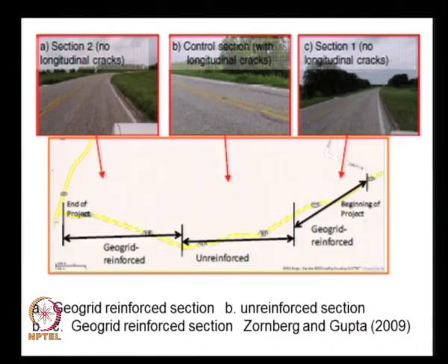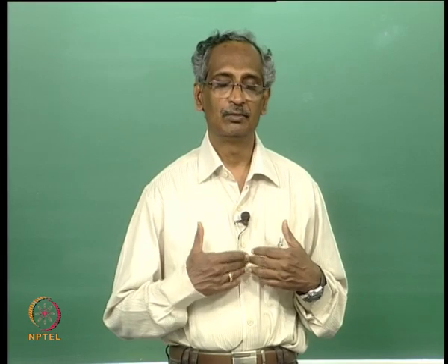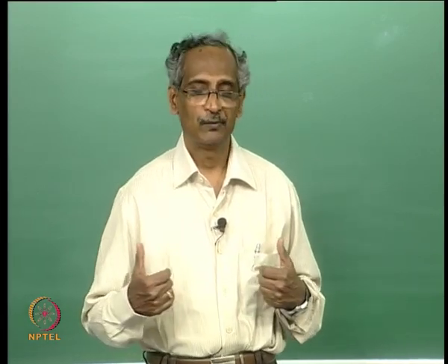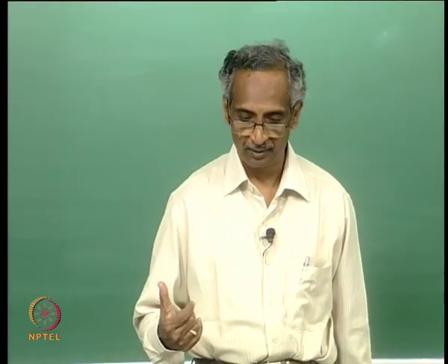They have tested 2 types of geogrids, both having different strengths, and they have seen that the geosynthetic having a higher strength but a low junction strength has shown some distress because the ribs have opened out at the junctions. So overall their conclusion is that the use of geogrids is a suitable solution to get a good performance of the pavements in the case of expansive soils.